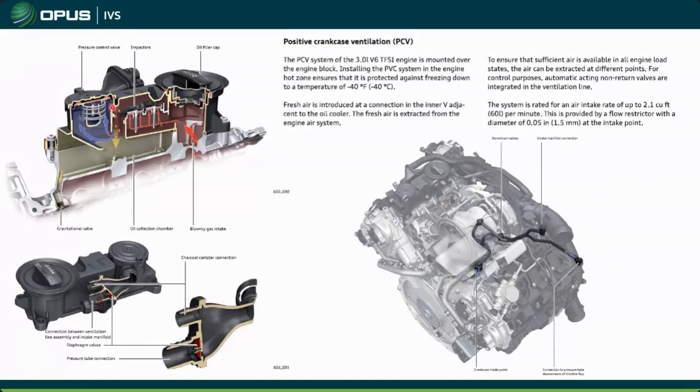And of course, those bigger droplets, as the air is coming around here, they can't make their way up to the pressure regulating valve or pressure control valve. They fall out of suspension, and then they go through this gravity valve back into the head, and drain back down into the system. So, kind of a little bit different setup, but essentially it operates the same.